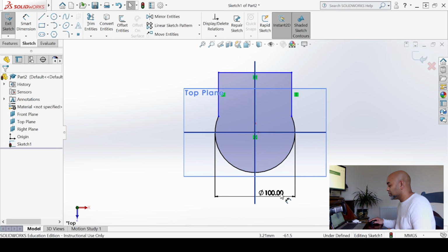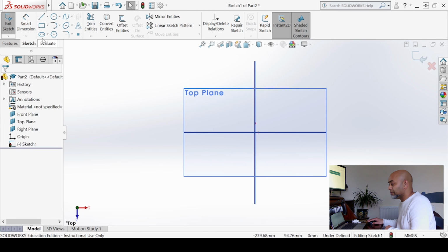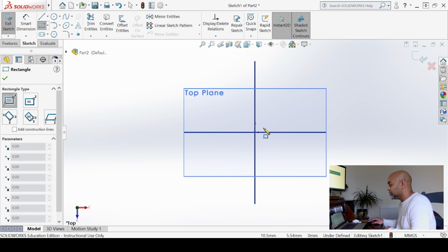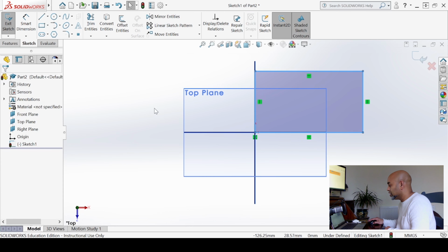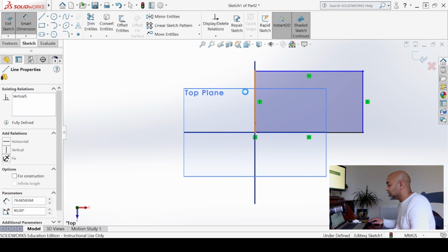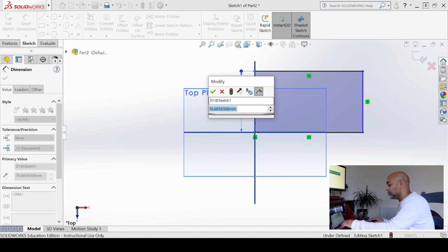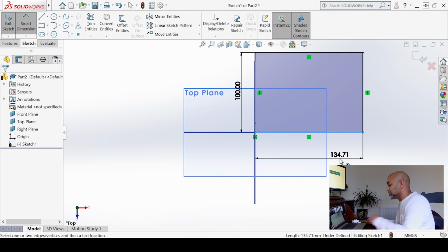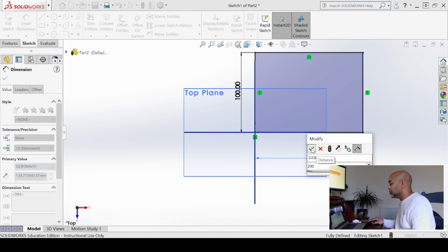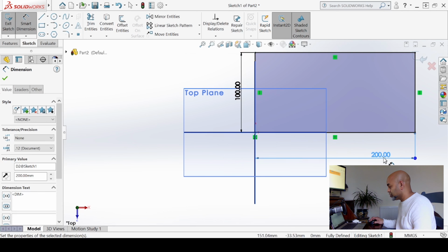We also made sure that every single time we do create some sketches, we were absolutely sure of dimensioning them fully to be able to get rid of any uncertainty in our design. That's what a good engineer generally aims for, is making sure everything is fully constrained with these green indicators there, and also with the help of some dimensioning options that we have looked at in some detail previously, and this then gives us a fully defined sketch.